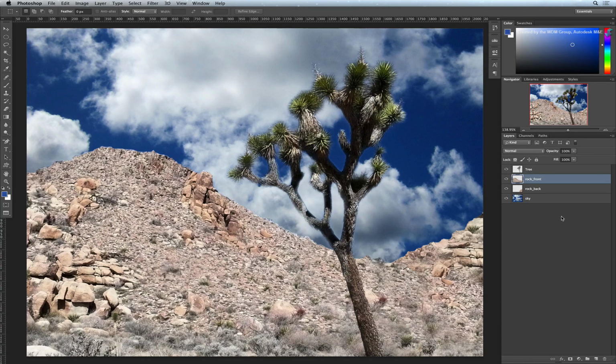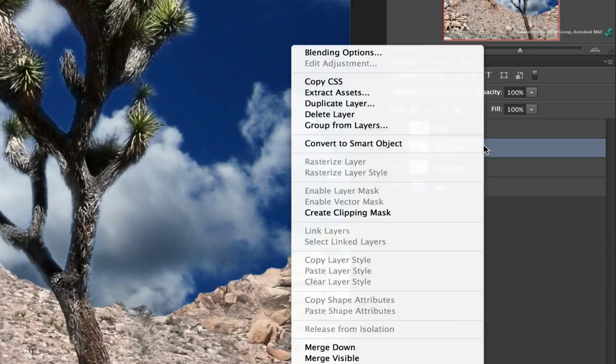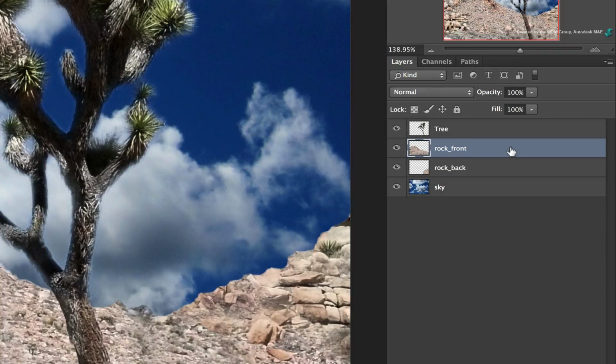So I'll just start off in Photoshop CC, where we can go through some of the preparation required to import Photoshop files into Smoke. It's actually nothing too complicated. All you need to do is ensure that all Photoshop-specific functions are rasterized into each layer. For example, all type and blending effects must be rasterized onto their respective layers. The only items you should retain are layers with their alphas. Blending modes between layers will import, so they should not be a problem.